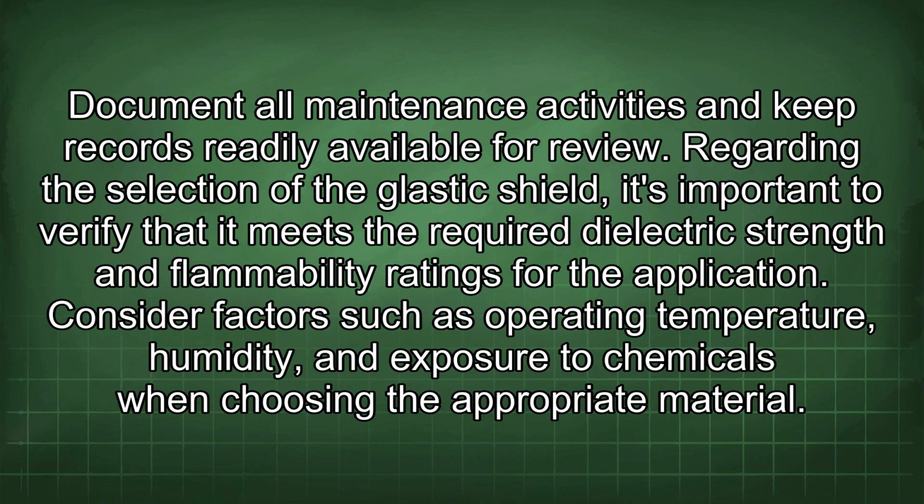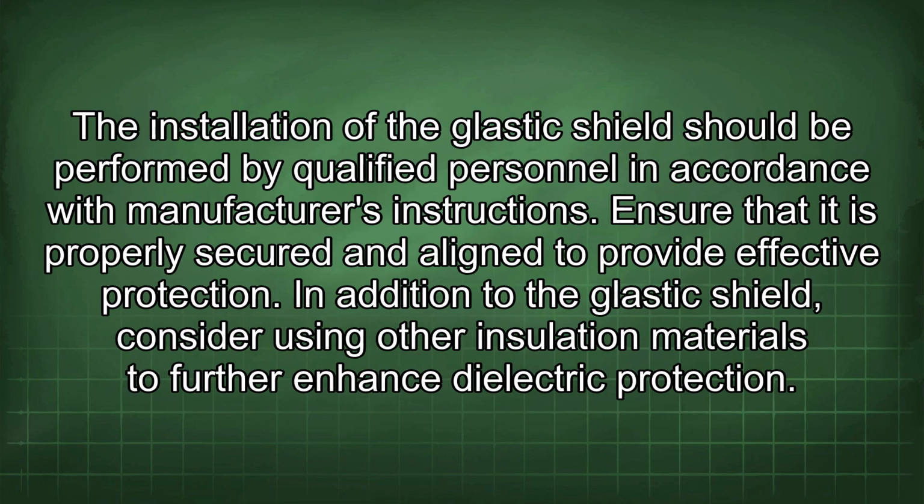Regarding the selection of the glastic shield, it's important to verify that it meets the required dielectric strength and flammability ratings for the application. Consider factors such as operating temperature, humidity, and exposure to chemicals when choosing the appropriate material. The installation of the glastic shield should be performed by qualified personnel in accordance with manufacturer's instructions. Ensure that it is properly secured and aligned to provide effective protection.